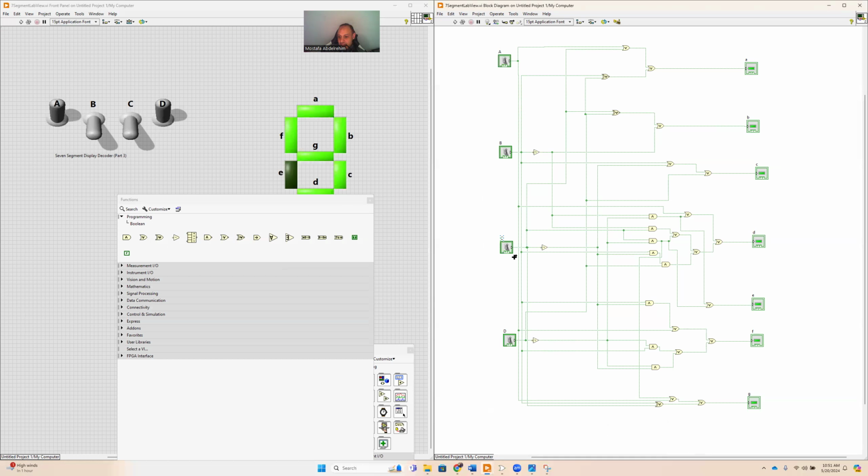So I have an example here. Here we are ORing the output of the XNOR, and let's go also for A, the output of the XNOR with the output of basically A or C, right? This is what we did. If this OR gate can accept three inputs, we can take this output here and just connect it to this OR gate directly, right? So we're going to save another OR gate. Let's do that. I'm going to remove this one here.